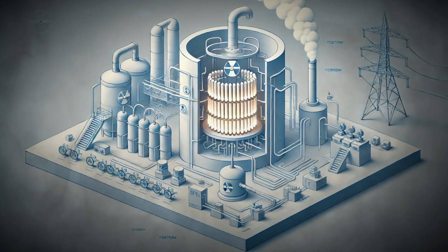Heat transfer in this context is based on conduction, convection, and phase change. Conduction occurs as the fuel rods pass their heat to the coolant in direct contact. Convection then carries the heated fluid through the pipes, and in systems designed to generate steam, the phase change from water to steam allows large amounts of heat to be carried efficiently. Engineers design the coolant loops with redundancy, multiple barriers, and extensive monitoring so that any problem can be detected quickly.